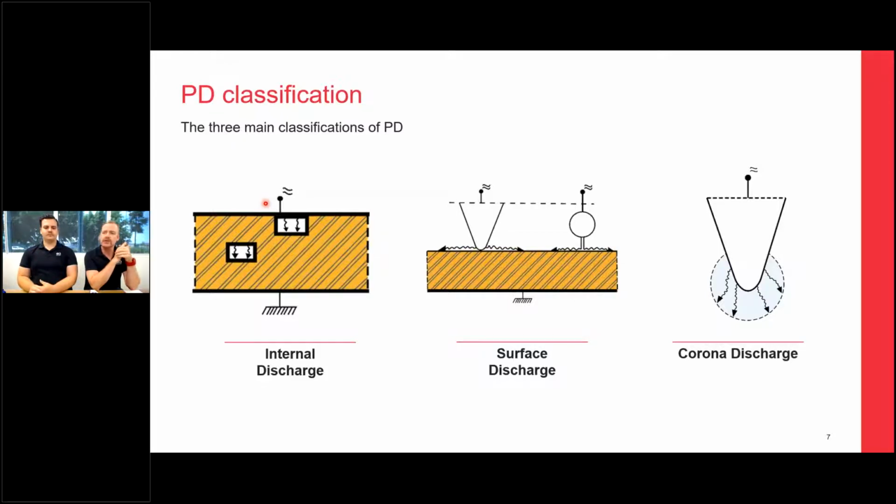But if you have corona on the inside of switchgear, it usually is a problem because it will create gases such as ozone that'll mix with moisture in the air and produce nitrous oxides and nitric acids and start to eat away at things in those chambers.